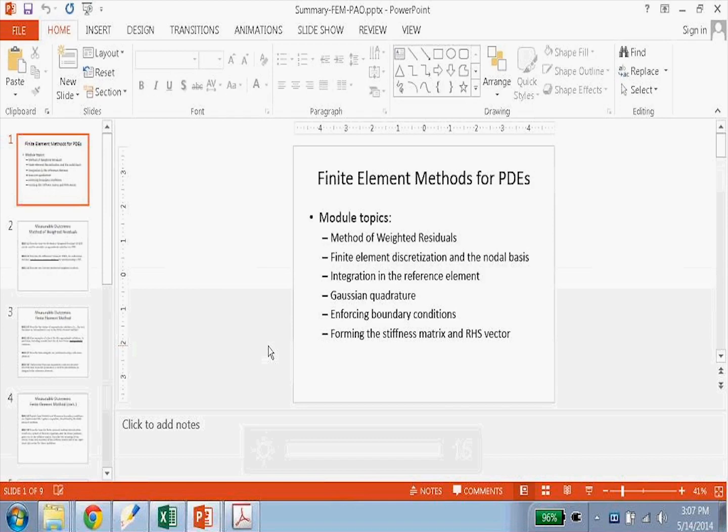Okay, so just as the last piece, bringing it all together, let's think about finite element for 1D diffusion. You need to make sure that you're clear that you can go through all these steps. So starting off with the governing equation: k dT/dx, differentiated again with respect to x, equals minus q on the domain minus L over 2 to L over 2, in x.